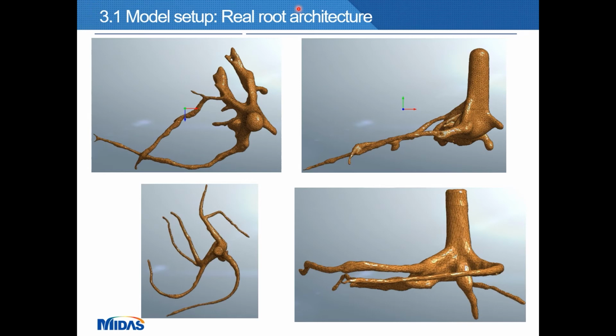We will move to the results section, but previously it's important to know that the values and the directions of the applied displacement in the numerical model correspond to those applied in the field test. Also, in the model the sand was considered a homogeneous elastoplastic material in accordance with the Mohr-Coulomb failure criterion. We also consider the rainfall and matric suction condition. For matric suction, we use Bishop stress, as explained in another webinar.